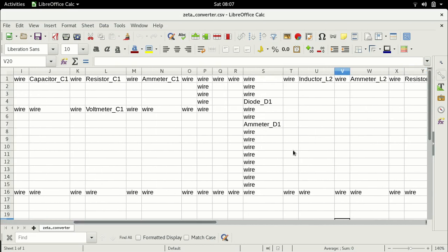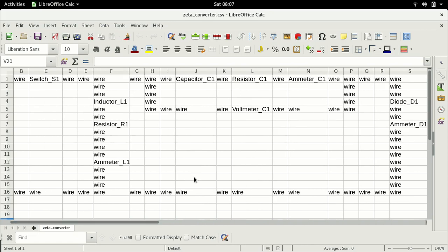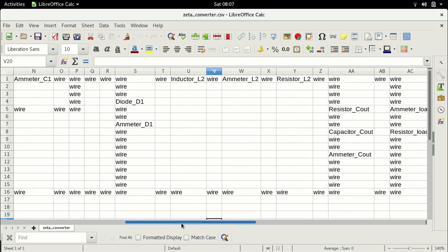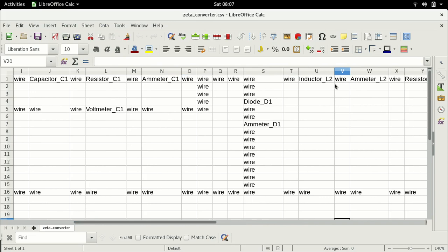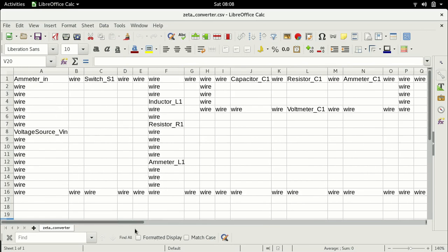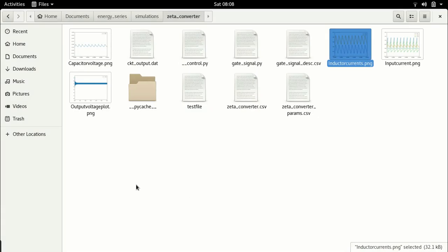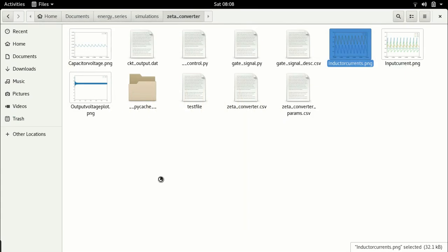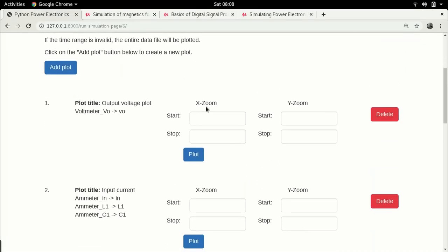On the other hand, the inductor L2 is in this larger path. So therefore, even if you have a low duty ratio, the inductor L2 is still charged by the capacitor C1, right? And similarly, the inductor L2 will freewheel through the output capacitor when the switch is turned off, right? So therefore, the energy that is fed to the inductor L2 is from different sources. So anyway, now that we have this, let's go and run our simulation again.